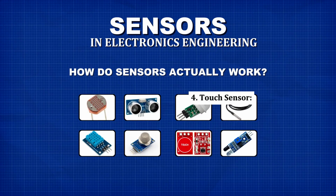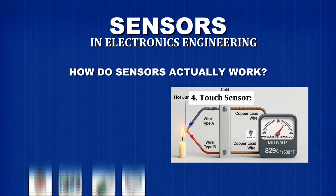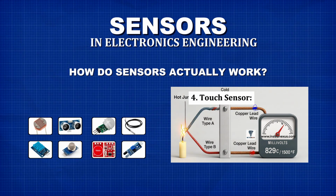So, how do sensors actually work? Sensors work by changing their electrical behavior when something around them changes. Some sensors change resistance, some sensors change voltage, some sensors produce current, some sensors send digital signals, while some sensors communicate with a microcontroller using data lines. For example, an LDR changes resistance when light falls on it. A temperature sensor changes its output when temperature changes. A microphone sensor reacts to sound. A gas sensor reacts to certain gases in the air. An ultrasonic sensor sends sound waves and measures distance.